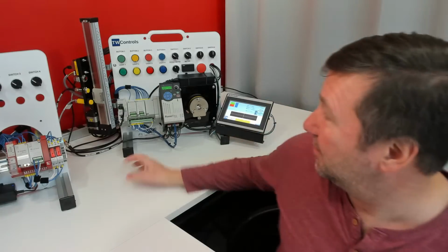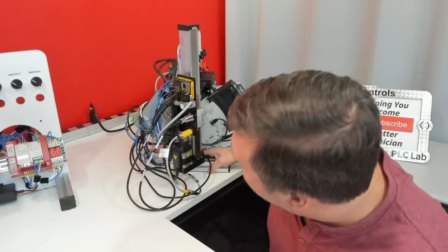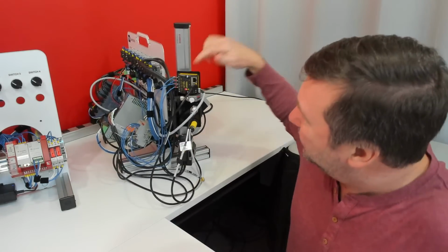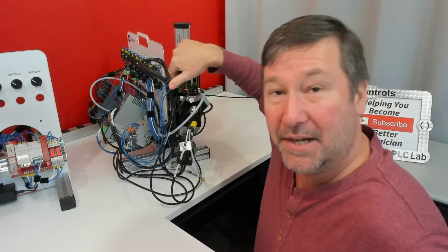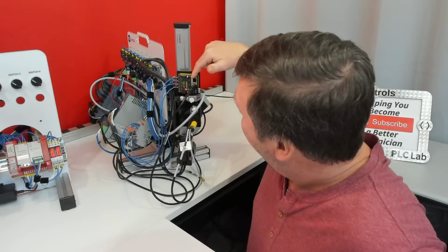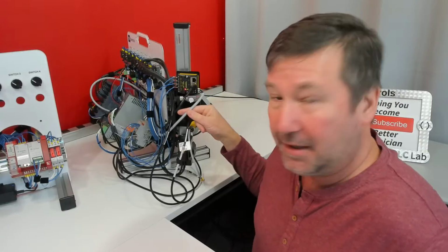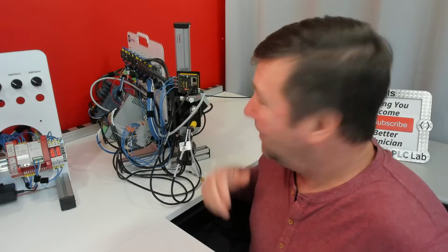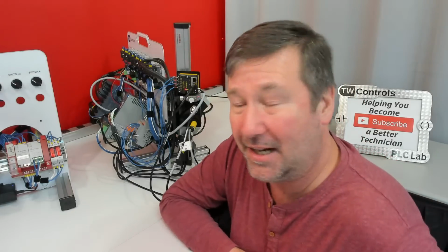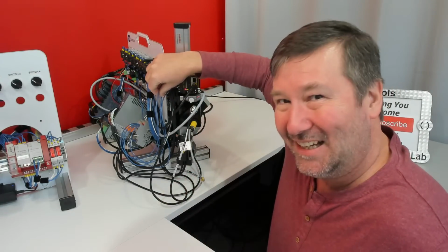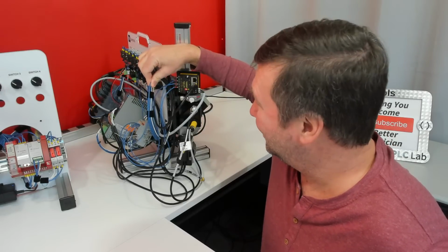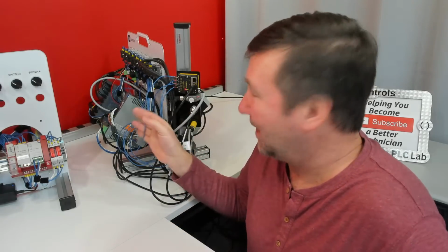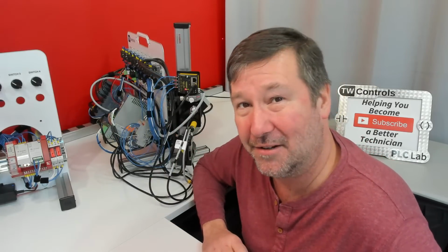So you're seeing a lot more, although this is the in-cabinet version, things like this IO-Link. This module could be out right near the machine or right near the part. It can pick up 4 IO-Link devices and then shoot it over Ethernet. So this way we only have to run a power wire and an Ethernet wire. And you can get these into 16 port IO-Link modules. And even then, one port on an IO-Link is not necessarily one sensor, because you can get sensor hubs for IO-Link, and we can pick up like 8 sensors on one IO-Link.